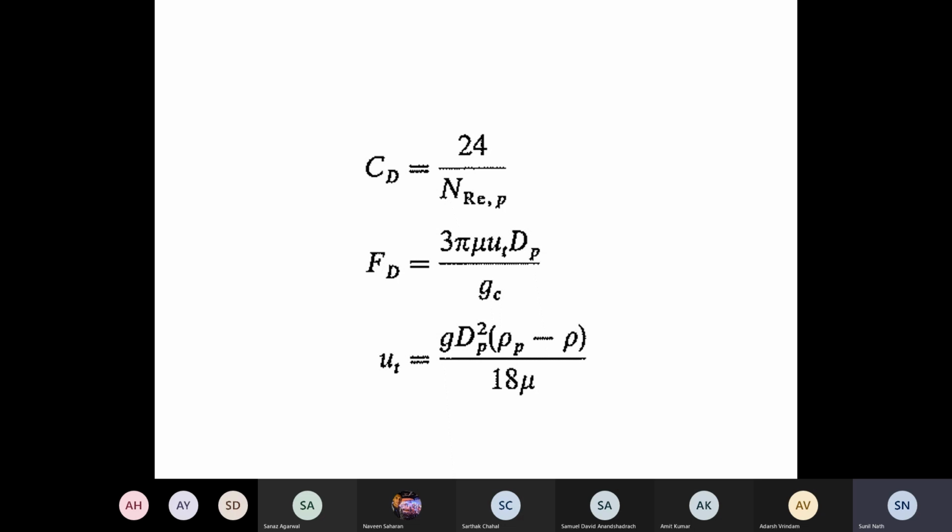Are my questions clear? So my questions are threefold. Firstly, take the general equation for the maximal velocity with acceleration term 0, limit that to the geometry of a sphere, then get the general equation with the 4 by 3 numerical value inside the square root. That's valid independent of Reynolds number or hydrodynamics. Then limit that further to RE less than 1 and derive these three equations that are on your screen. That was question 1.